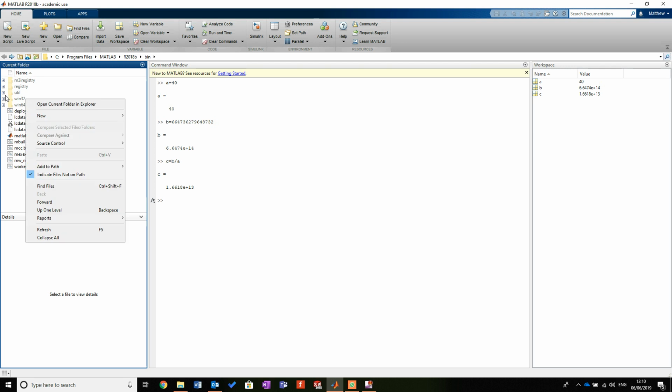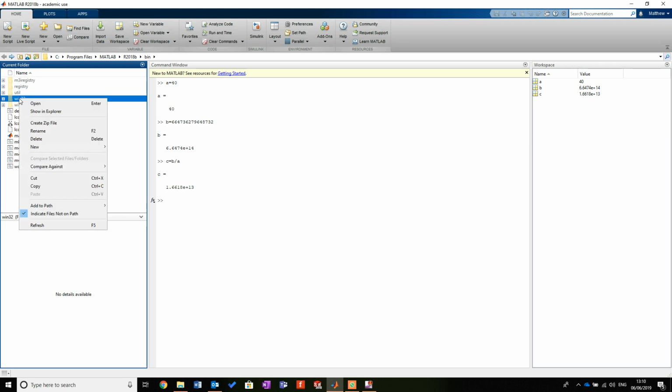One thing about this is when we move into Sim Multibody, we'll be using CAD models. We will use models that have been pre-generated. We will build the model, we will simulate the model, and we'll look at the reactions from each system. Now the issue is, if you're going to import something like an STL file, or a STEP file, an IGES file, any of these pre-written translation files, you need to be able to tell the system where these files are stored, or else it will come out and go, no, not doing that, not happening. And it can be frustrating.